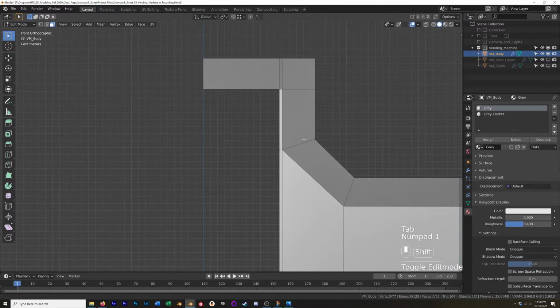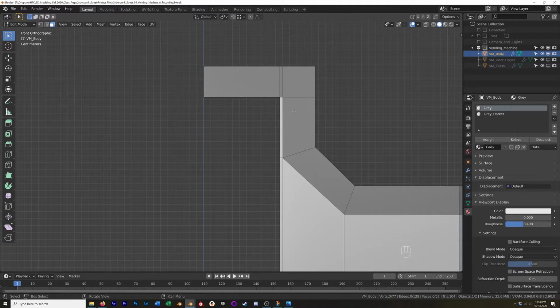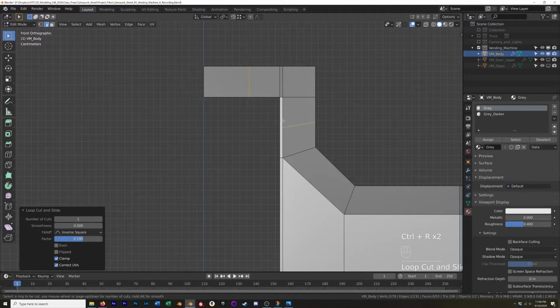So now we need to get this working. This I think I am going to use the other way. So I'm going to add in a couple of edge loops here. See, this one's at an angle, so I'm going to hit E to keep it even and F to flip it so now it's even with the top. Going for roughly squares here. Good.